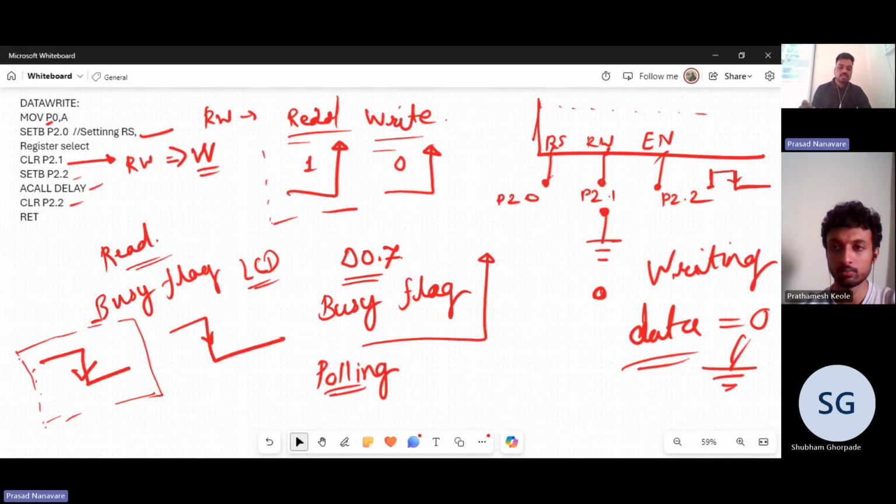There is this one column that I have given you, which has the command and its function. Like 0x01 means clear screen. Similarly there will be a command to take your cursor to the second row. So when you are writing a roll number, first you have to give the command to bring the cursor to the second row, and then you write it. So this is how it is. You basically check the command column and then you do it. Okay, it's very simple. You will know it when you do it.